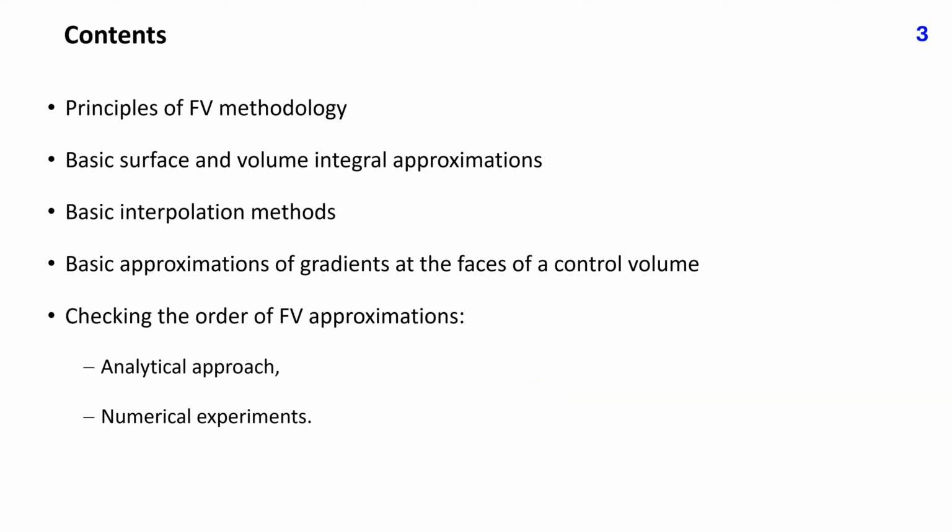In this lecture, I'll first describe the principles of finite volume methods and then present the basic approximations for surface and volume integrals. The next step are basic interpolation methods, which are needed to compute convection fluxes, and approximations of gradients at control volume faces, which are needed to compute diffusion fluxes. I will show how the order of integral approximation and interpolation can be analytically determined using Taylor series expansion, but at the end I'll also present numerical experiments by which this can be demonstrated.